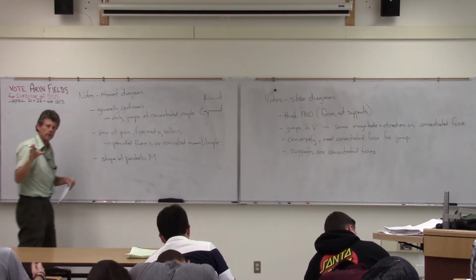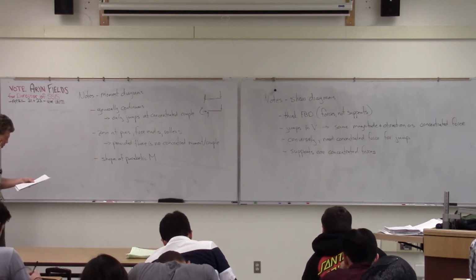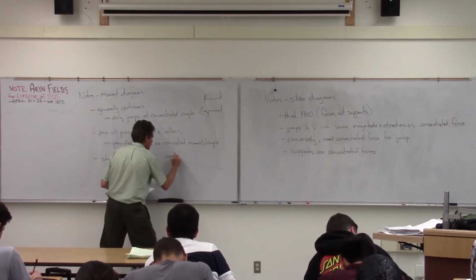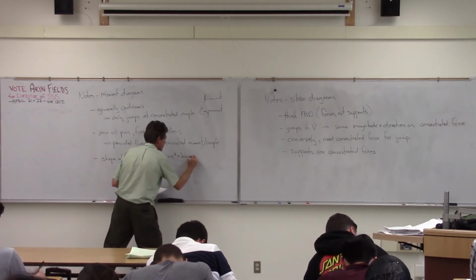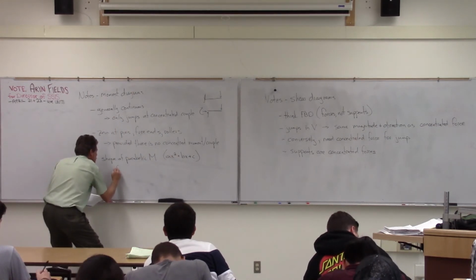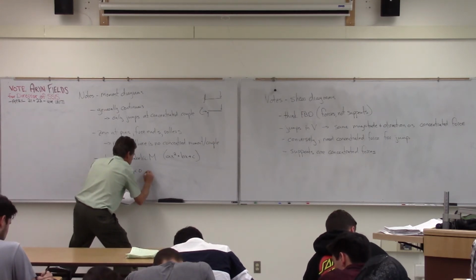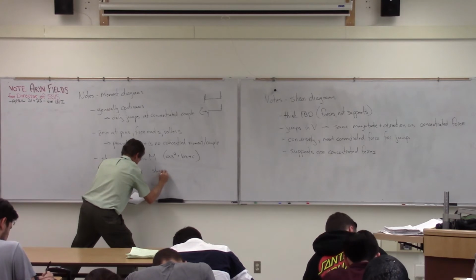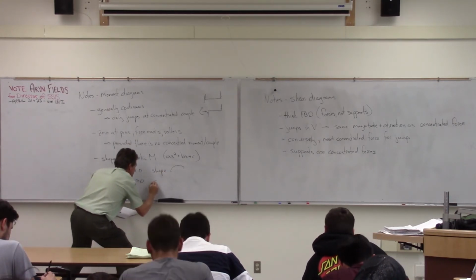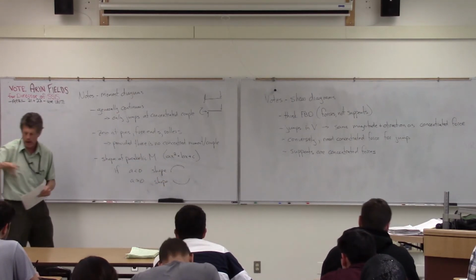Now, a lot of your moment diagrams are going to be parabolic because most beams are supporting some sort of uniform load. So if we have it in that form there, going back to your mathematics approach there, when you draw the shape, that's going to be important too.